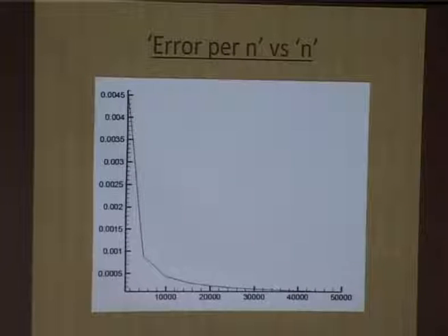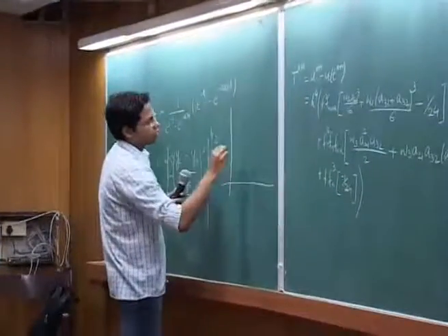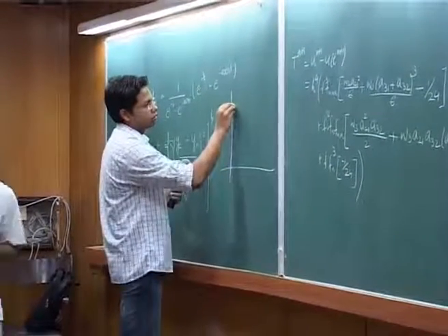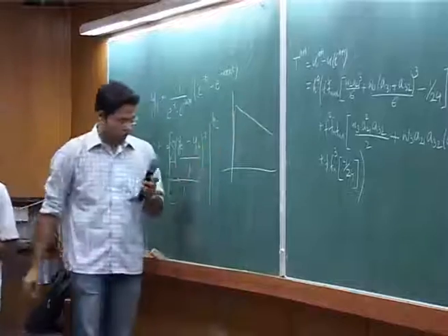So based on what we just heard, it would probably be a good idea to keep it in the inner part of the boundary layer. Yes, sir. In the outer part, we could be a little more liberal, right? Yeah, exactly. And probably even that 400 limit is not a correct limit. If I were to do it, I would get the solution in 200 points by having variable spacing. Yeah, so that's how it should be.